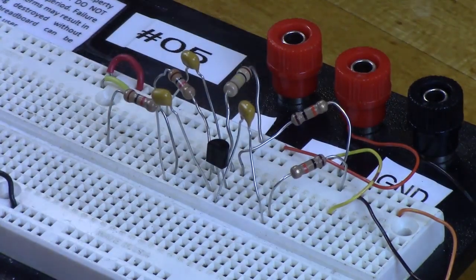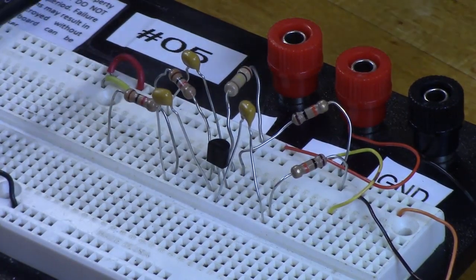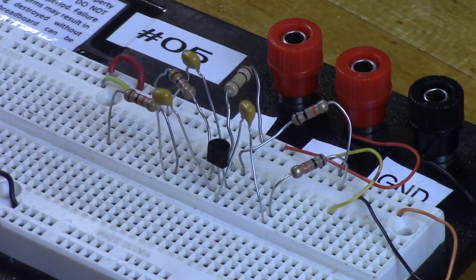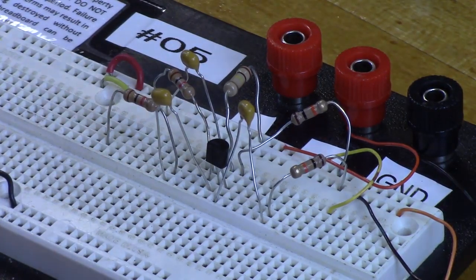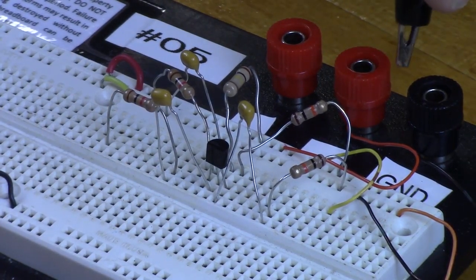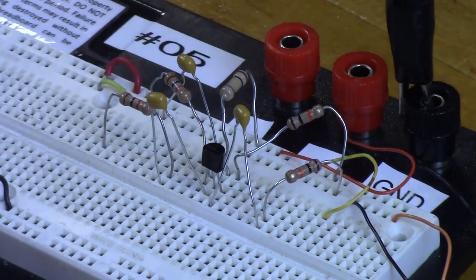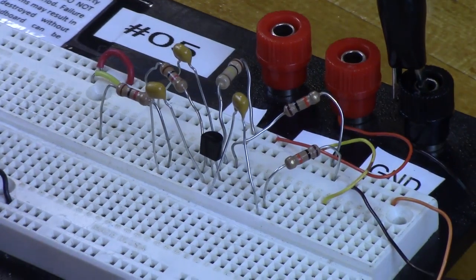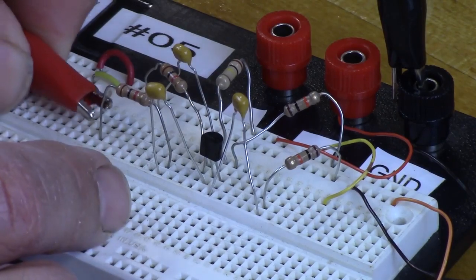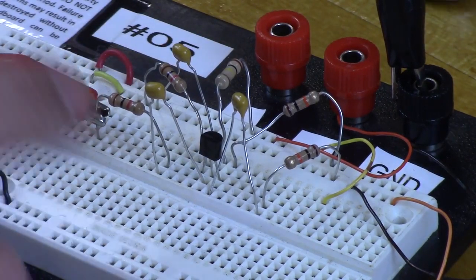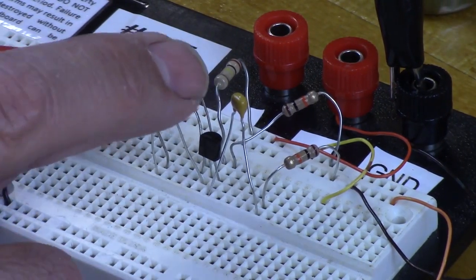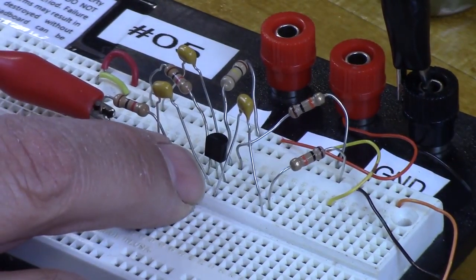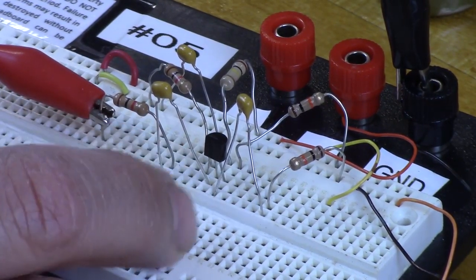We have our coax. We're going to plug it in here, and we're going to just clip this lead to ground. We'll put it there temporarily. And we're going to clip this lead onto the resistor, like so. So we have VS coming through RS through C1 to the base of the transistor. Okay, and then from there we have R1 going up.